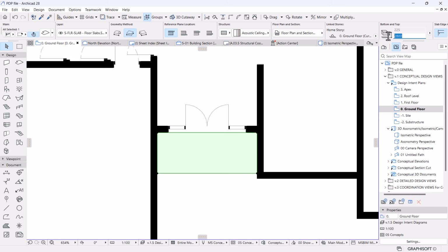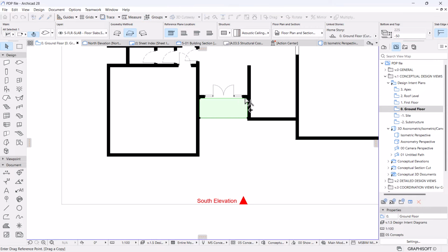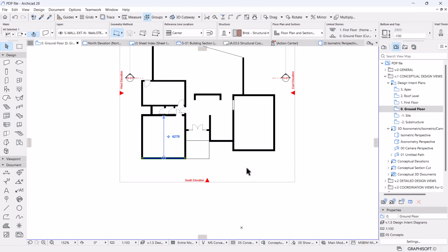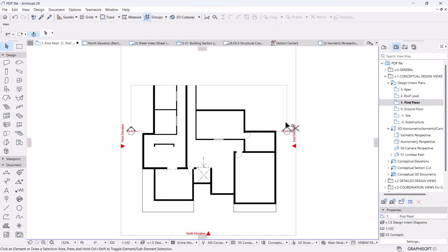Then I'm going to drop it. It needs to be dropped by -50. Then you can also have another one there that is going to be -100. Okay, then we all have our slabs in place. I'm going to copy this to the upper floor. Then paste it there.